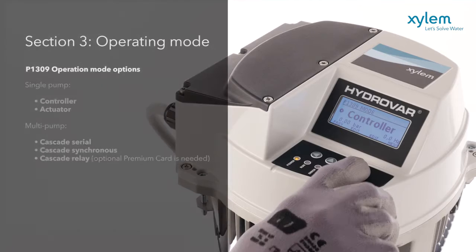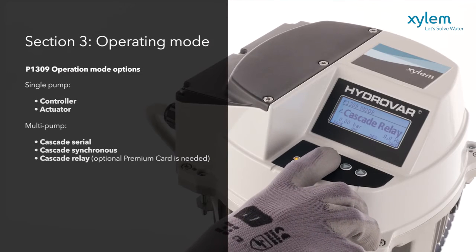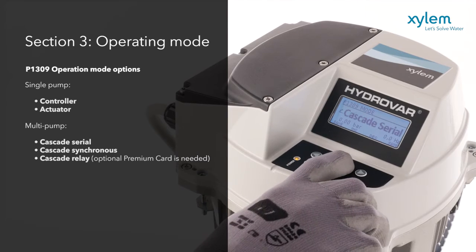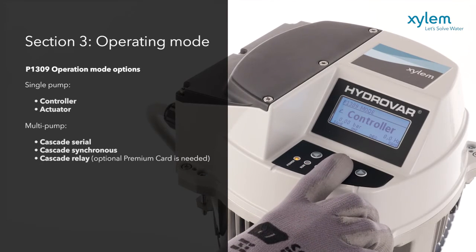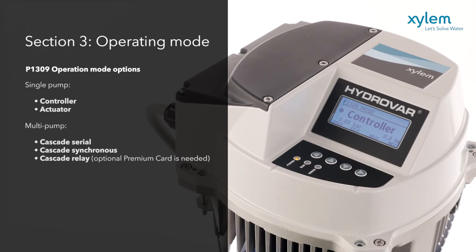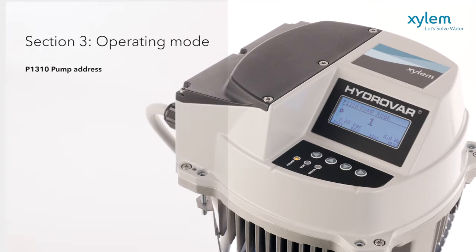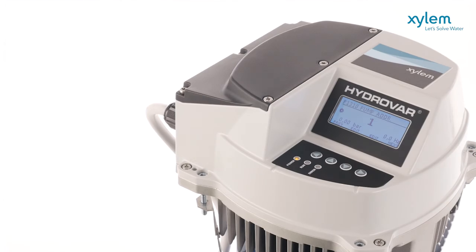The control options are displayed, with the default being a single motor. Here, the choice is offered to set the options for multiple pumps, including Cascade Serial and Cascade Synchronous. For a single pump, you can select between control or actuator mode. In multiple pump systems, Hydrovar allows up to 8 pumps to be connected via the RS485 interface, making each pump totally independent if a failure occurs to either another pump, Hydrovar, or sensor transducer. Note that a screened cable is required along with a unique pump address for each pump.